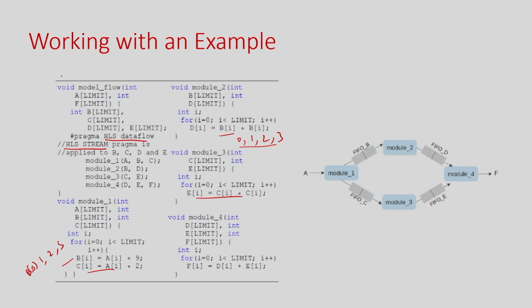If you say that you want to make it a streaming application, then ping pong will be the default option, but if the producing order and consuming order are the same, I can make it a FIFO, in which the buffer size will not be double. In ping pong 2 buffers are needed, in FIFO I need only 1 copy, and most importantly these modules do not have to wait for the entire data to be produced. Whenever one data is produced, because the consumption will be in the same order, it can be consumed immediately. So, coarse grain parallelism can happen at a much inner level.